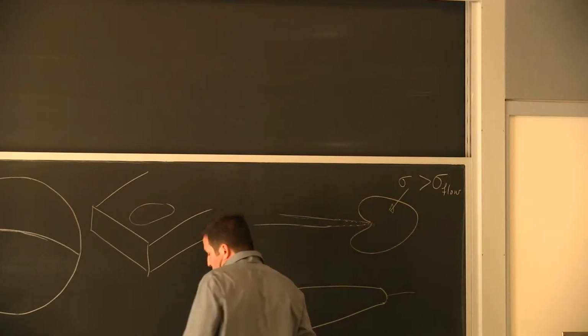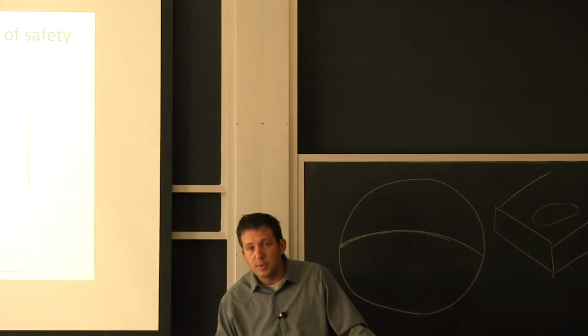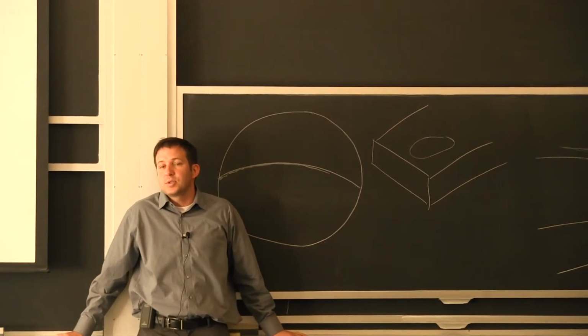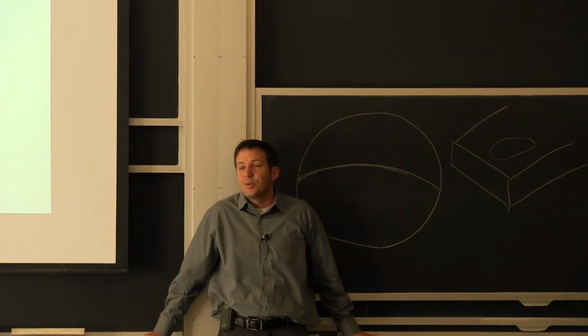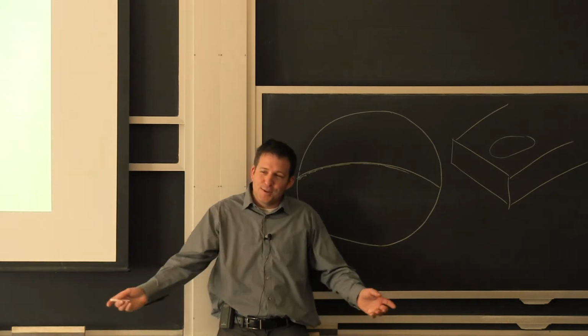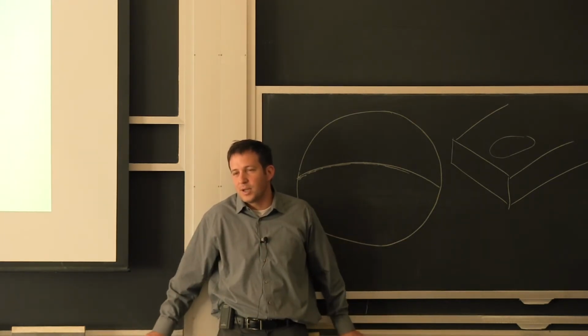So the alloying elements, other than aluminum, magnesium, copper, will have some influence. They're all going to affect the chemistry of what's going on in that crack tip. So there are some chemistries where you can almost avoid the stress corrosion cracking, but then you don't have all the strengthening benefits. So it always ends up as a compromise.